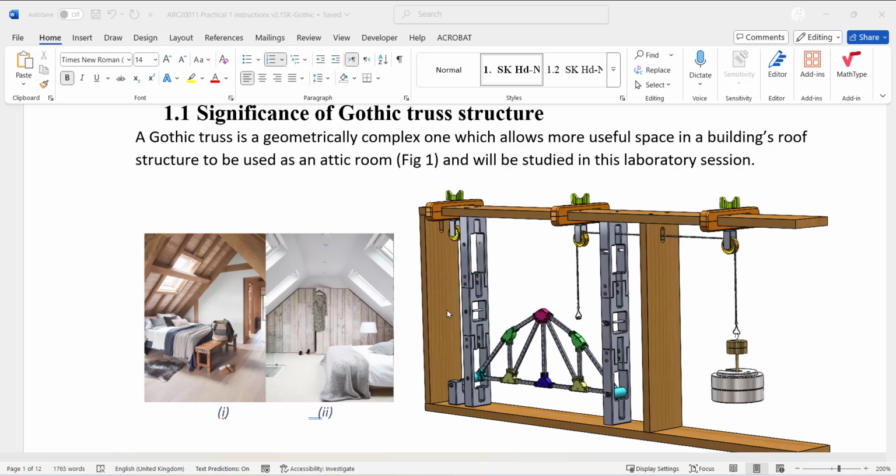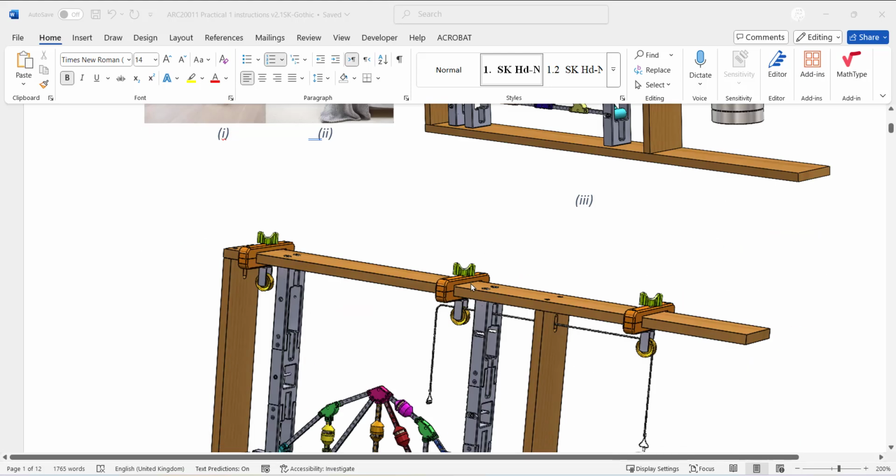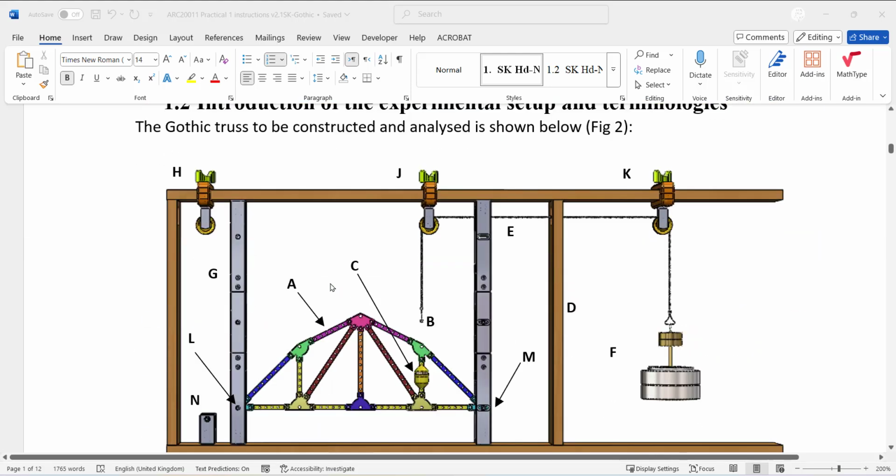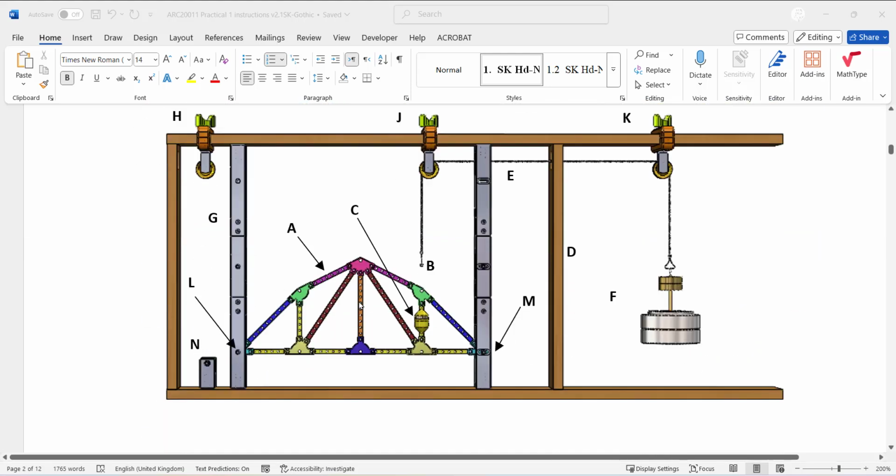And on the left-hand side there is a vertical space which helps you to put a selected member and apply a load to the same system by cable and find out what is the limit of that member. So by increasing the drop weight, you increase the load, and eventually at one certain load this member is going to be collapsed.